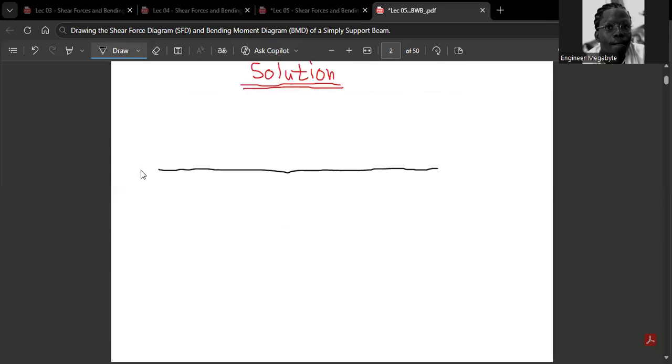At the left hand side, I can put this over here. That is my horizontal force at A. This becomes my vertical force at A. In this case, I'm going to use reactions. You understand me? And then we can say that this is our horizontal force at A, HA. And then this is going to be my reaction A. This is also going to be my reaction D. This is point D. Don't get confused.